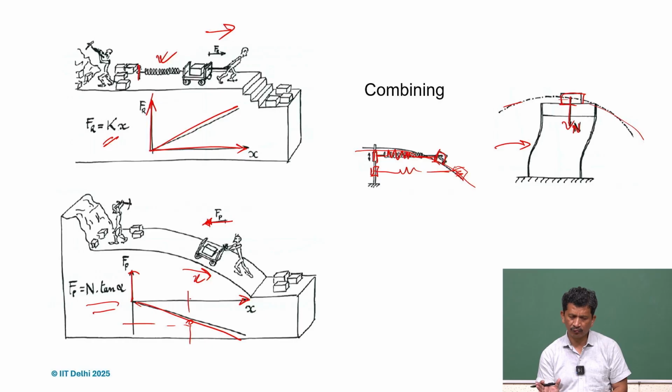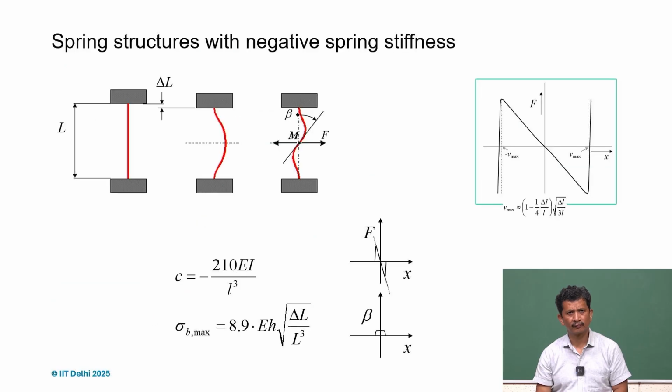So with this arrangement, parallel guidance with the negative force can give us some negative stiffness, and depending on this force N, we may be able to fine tune it and achieve near zero stiffness.